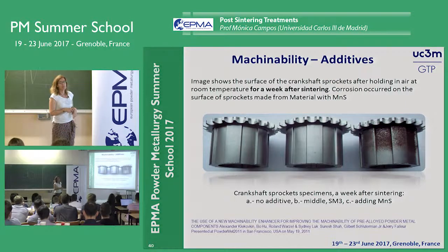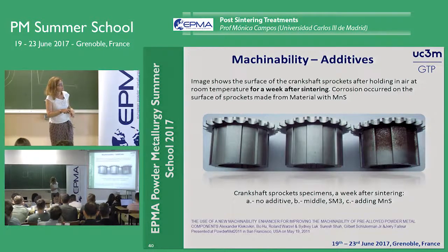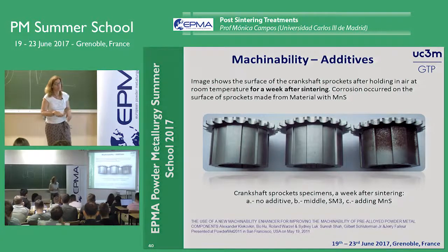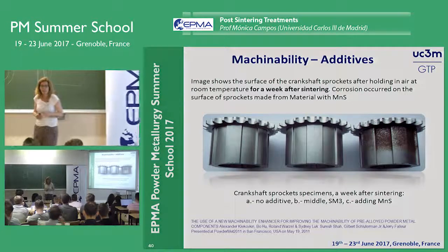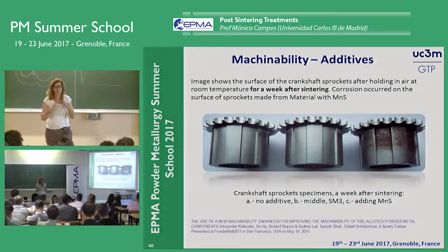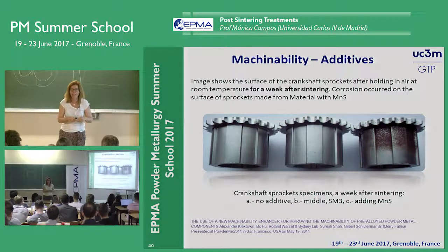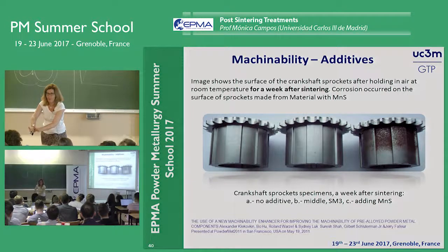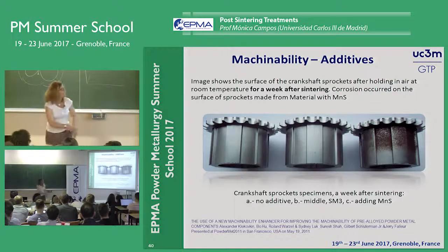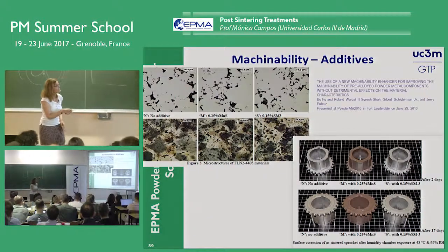This is the same component without additive. This is with a specific additive designed to avoid this stain. And this is the same component with manganese sulfide, in that case after 1 week from the sintering process. If you are a customer and you see this component, then you reject the component directly. No? In the microstructure, there is no effect.